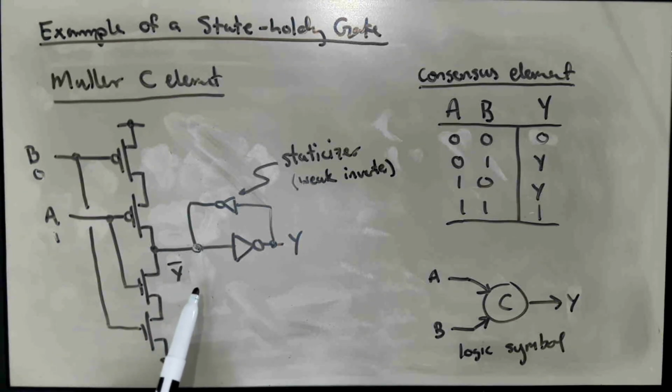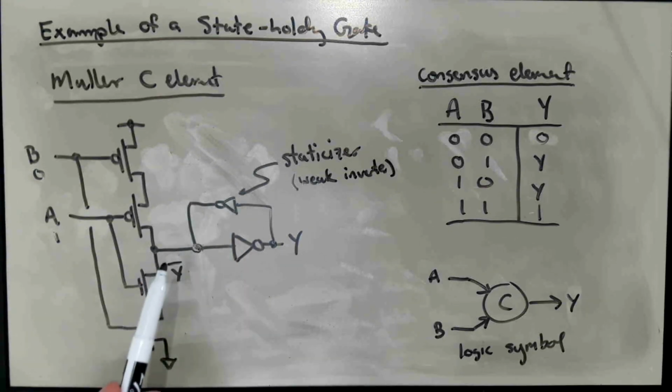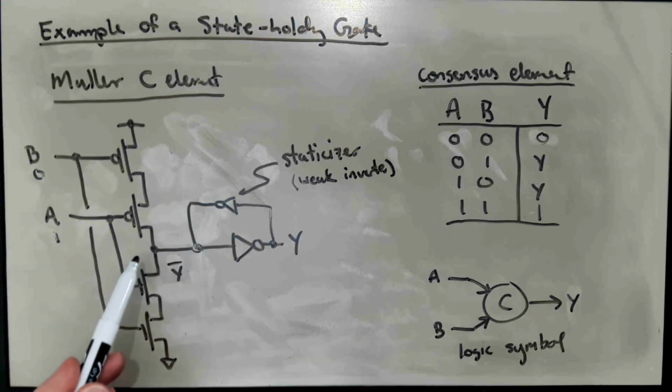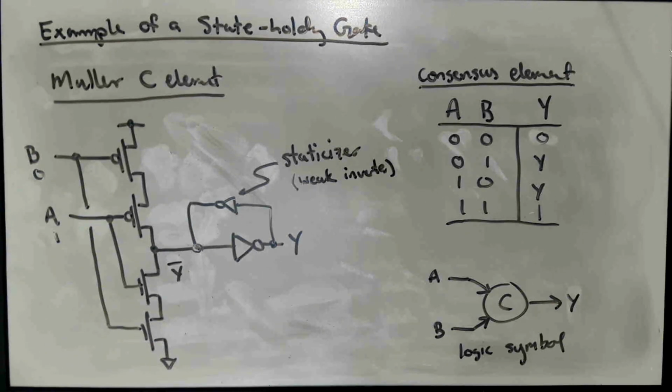Or one other approach would be to take the same idea that we had with the SR Latch that had the writability problem. We could introduce some additional transistors here in the feedback inverter to cut off the pull-up or the pull-down under the appropriate conditions when we want to actually change the state or need to change the state of the C element to make a fully static C element without the writability problem at the cost of introducing a few extra transistors. Okay? So this, I think, will conclude our little foray into transistor level digital logic design.